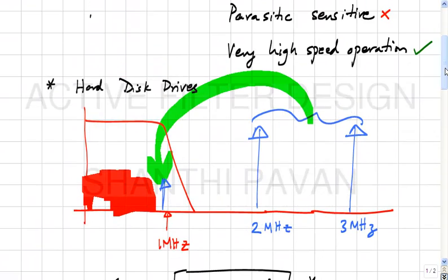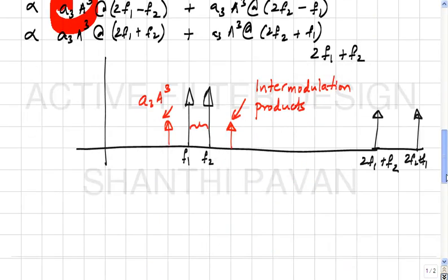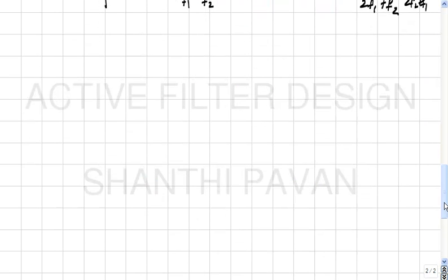So, it is very important that the filters that you use have adequate linearity, right. Now, speed is no longer an issue because the bandwidths of these systems are somewhat small. Okay. Now, the question is, how do we go about realizing these filters? Should we burn more and more power in the GMC filters and make them linear, or is there a smarter way of doing things, right?